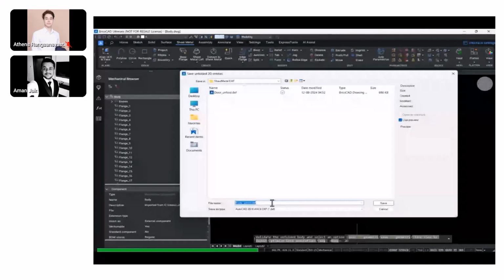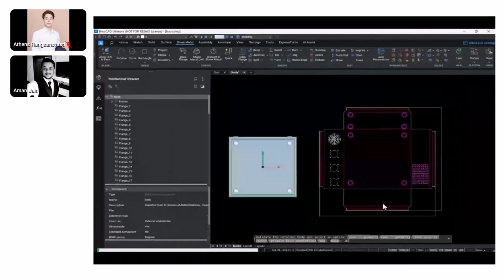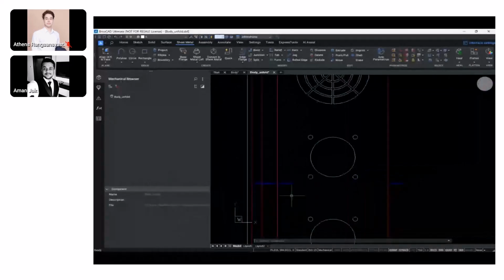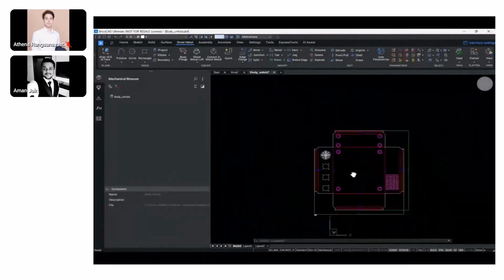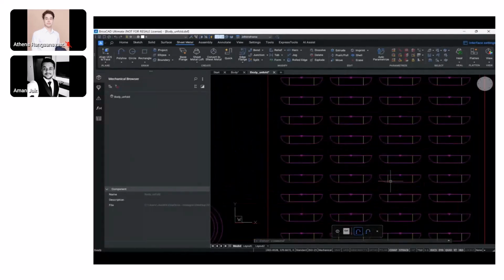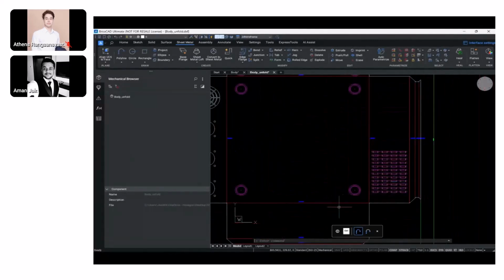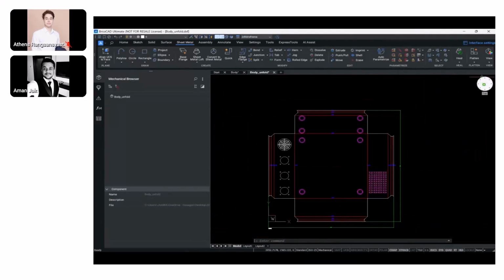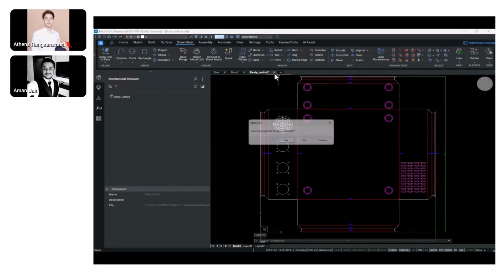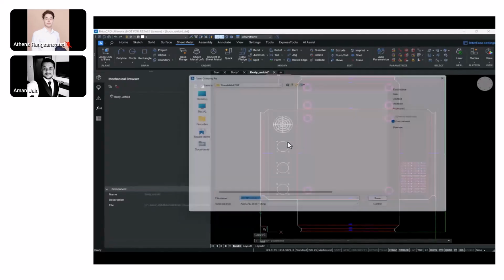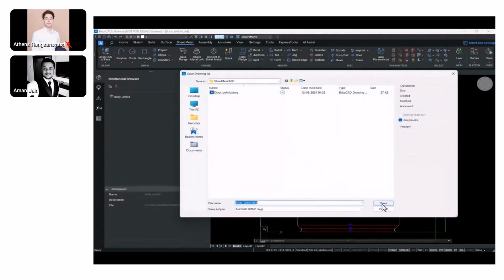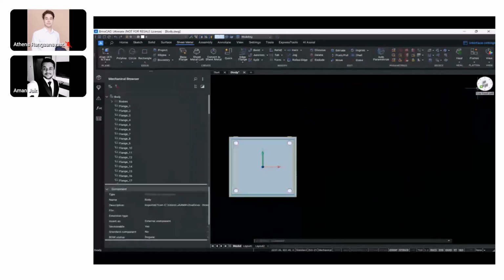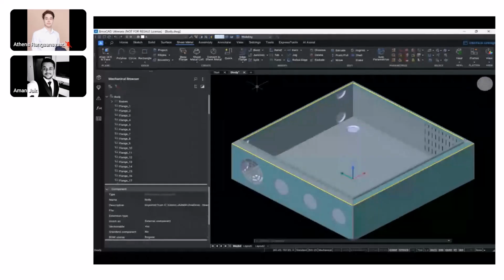And I can save this as a DXF like we did for the earlier geometry. And as we can see, we have the bend line annotations, the angle of the bend, the radius of the bend, the form features in place. Of course, there'd be need to manually dimension it a bit, but then we get the exterior dimensions. So we come to know how much of a material or what length of the material, what area of the material we'd need to create this kind of geometry, right? So that is something that we have in place with BricsCAD. The exterior dimensions are there in place already.